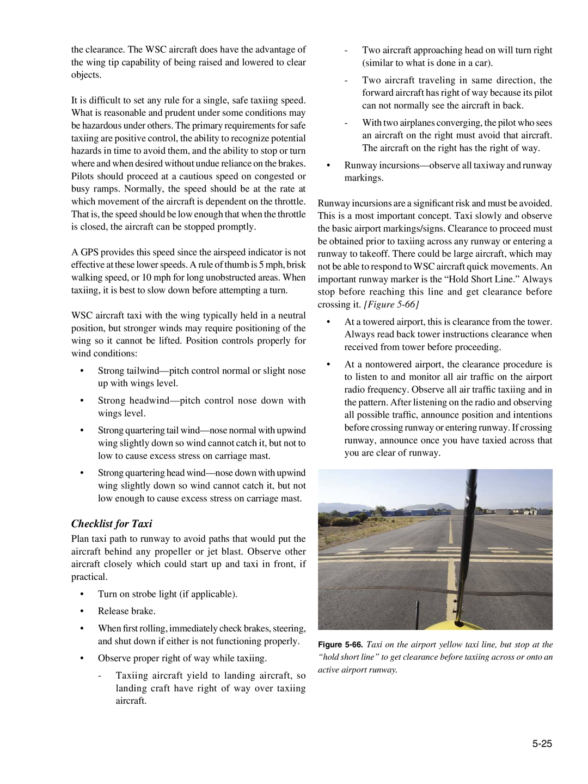An important runway marker is the hold short line. Always stop before reaching this line and get clearance before crossing it. Figure 566. At a towered airport, this is clearance from the tower. Always read back tower clearance instructions when received from the tower before proceeding.